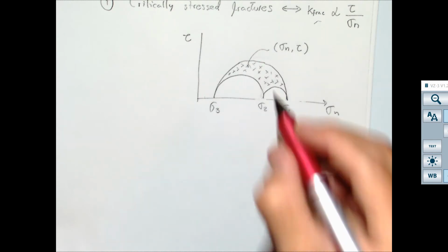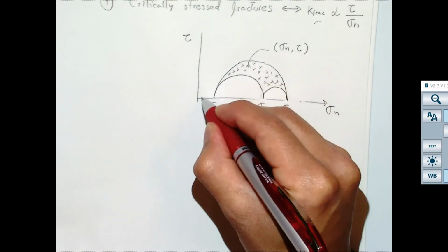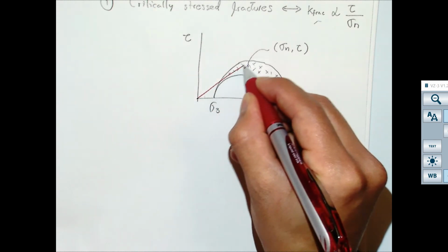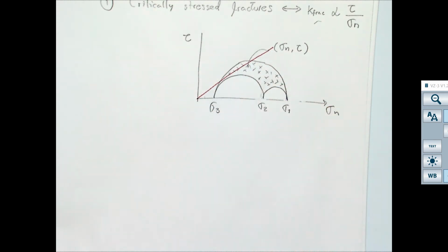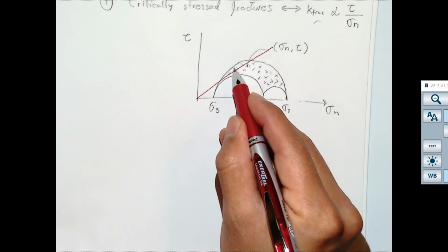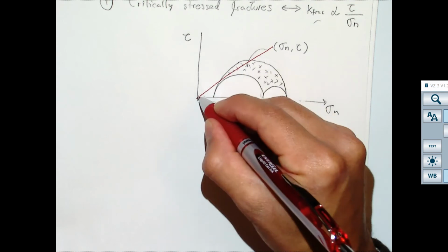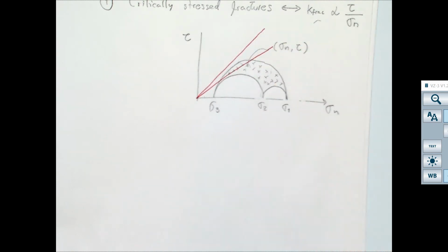And for that, I'm going to add something that we didn't add before. And sometimes I remember one of you asking me about this. What does it mean that some of these points are above the line? Well, in theory, you cannot be above a shear line. But as you know, for all real materials, their properties are not just a unique number. There is always an uncertainty. There is always a heterogeneity.